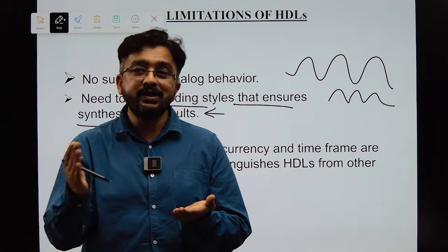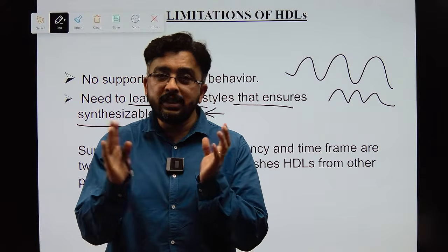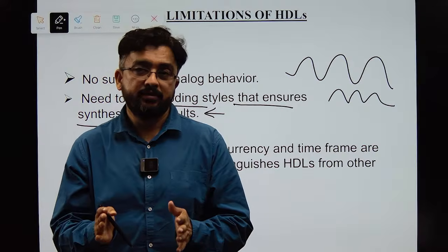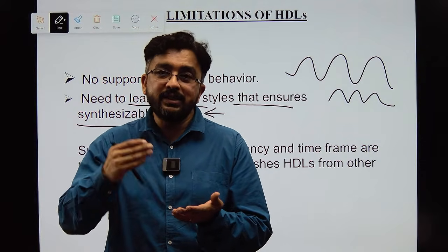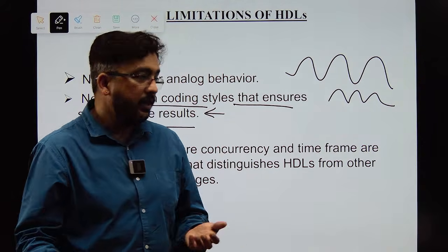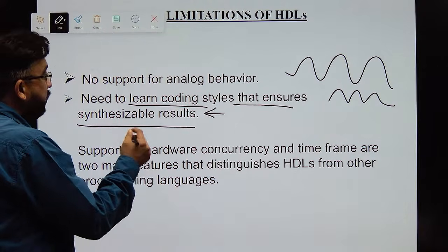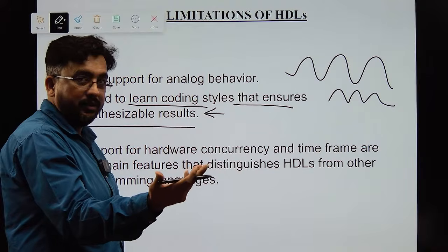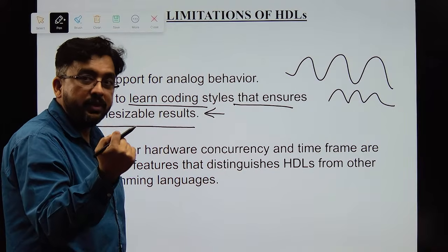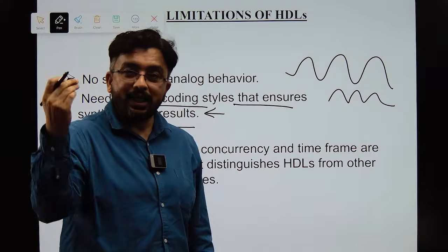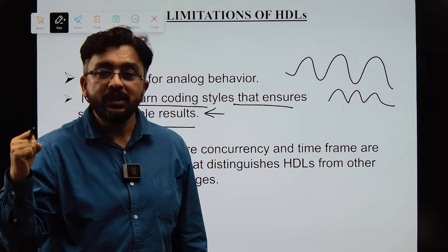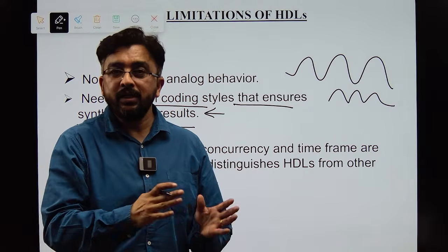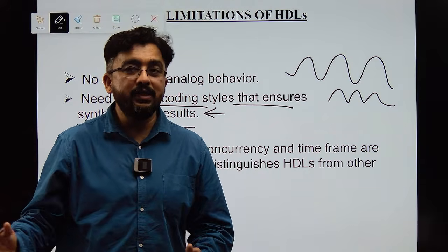That is called non-synthesizable. But those syntax constructs help you understand the simulation. So you need to learn a lot of syntax, like task and function, like FSM modeling, like loops, like case, like if. There are many, from beginner level to expert level.